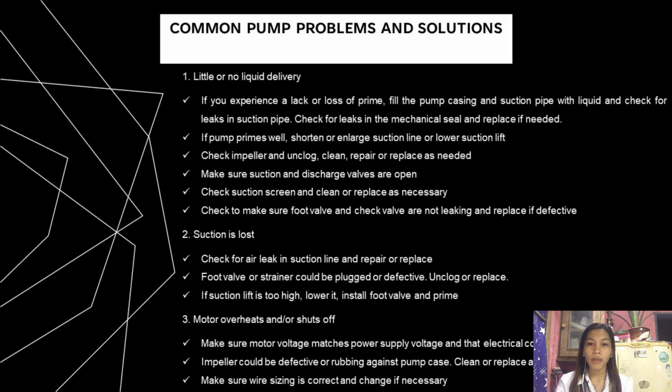Third common problem is motor overheats and/or shuts off. The solution for this is make sure motor voltage matches power supply voltage and that electrical connections are tight. Impeller could be defective or rubbing against pump case. Clean or replace as necessary. And make sure wire sizing is correct and change if necessary.